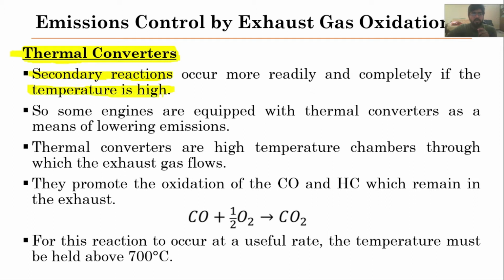That is why they are called thermal converters, because at very high temperatures, the desirable reactions, like conversion of carbon monoxide into carbon dioxide and conversion of unburned hydrocarbons into carbon dioxide and water vapors, will happen. So some engines are equipped with thermal converters for the purpose of lowering the emissions.